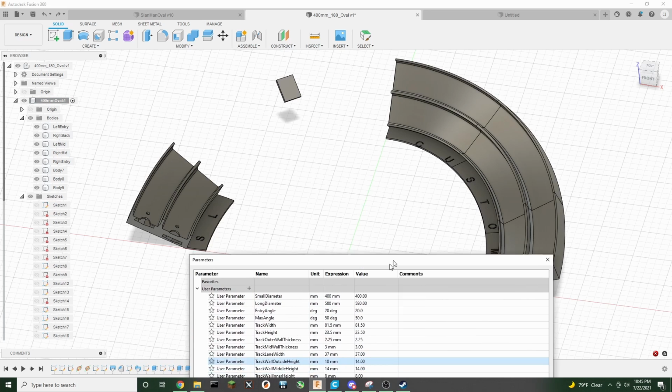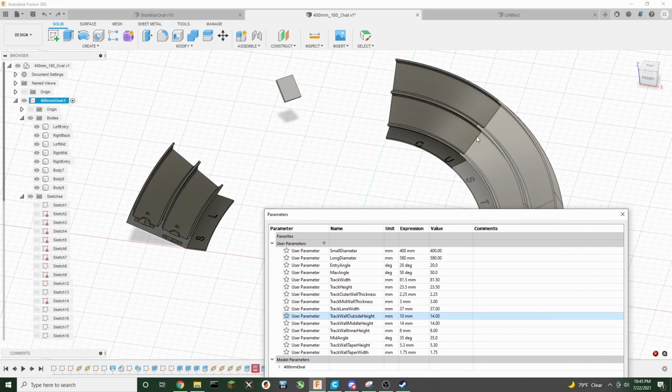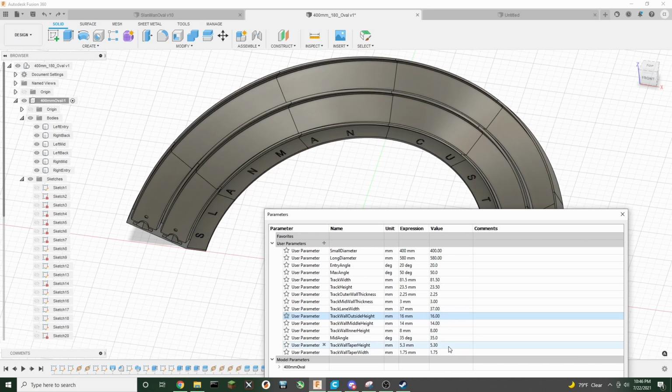And if you remember from the video, we had to add our middle sketches to give it a hint. That's simply because this geometry couldn't figure out how to line up with this geometry, and then it couldn't figure out how to rebuild everything. What's funny is you can't just undo it by going back up to, was it 16 or 18? It might work, but it likely won't. In this case it did.